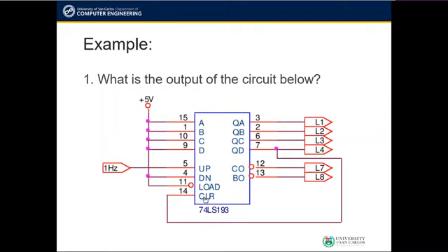The CLR or the clear input is connected to the output QD of the counter. QD becomes 1 for the first time during the count of 8. So when the counter reaches the count of 8, you will not see it at the counter output anymore, because at that time the clear input has been triggered already, thus the counter resets back to 0 and then the counting continues.